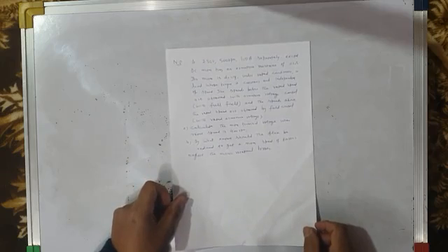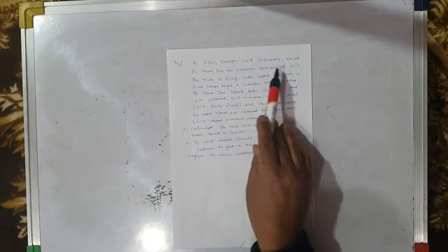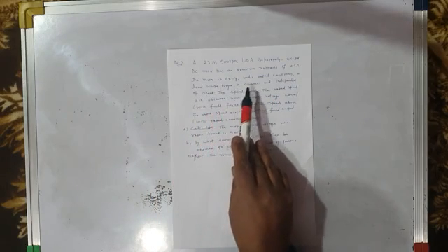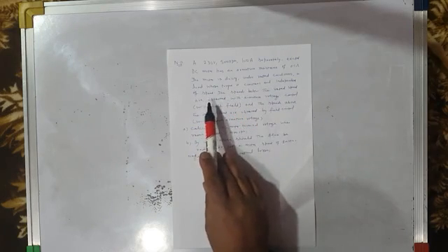Let us try to solve a numerical problem. This is the numerical problem, for a separately excited DC motor that we studied in the previous lecture. I will read the problem for you. A 230 volt, 500 rpm, 100 ampere separately excited DC motor has an armature resistance of 0.1 ohm. The motor is driving, under rated conditions, a load whose torque is constant and independent of speed.